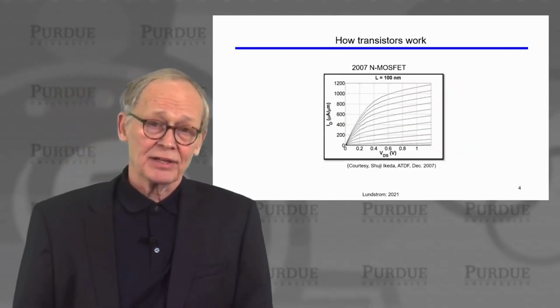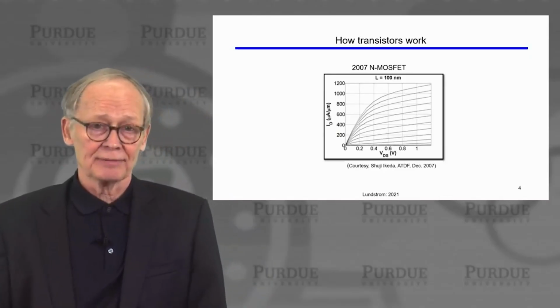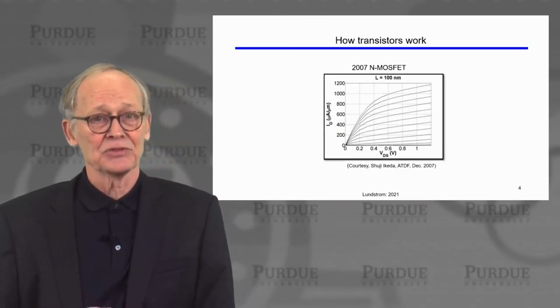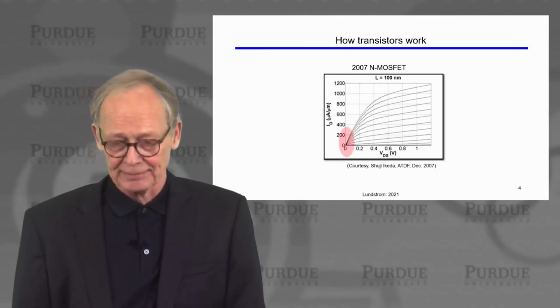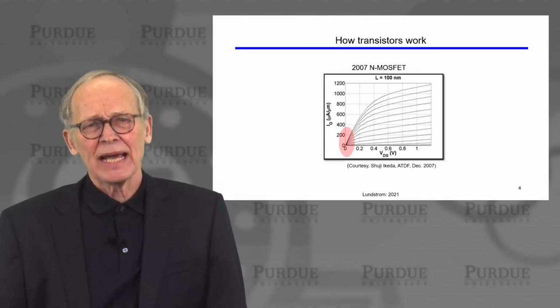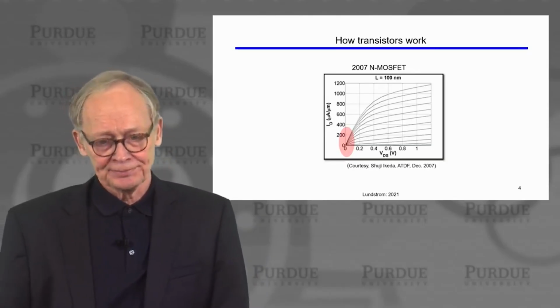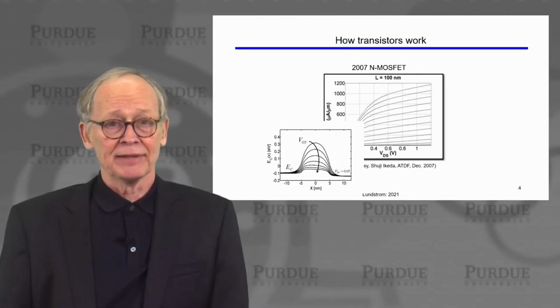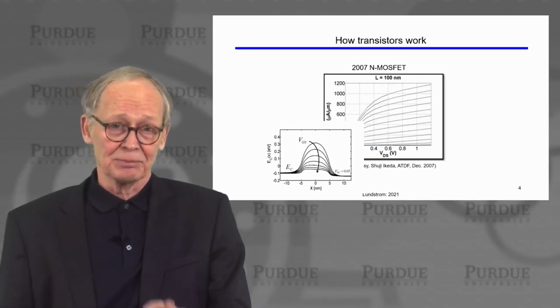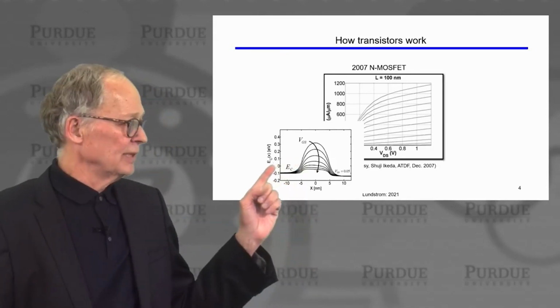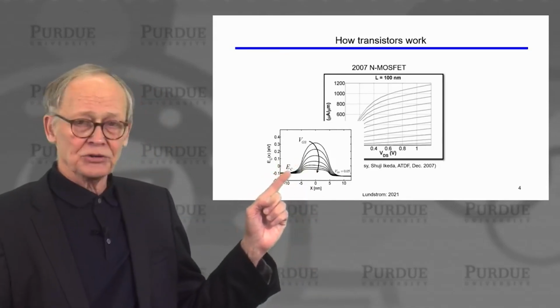Well, these are the IV characteristics of a typical MOSFET. Pretty representative of what we might still see today, although channel lengths are quite a bit shorter today. If we ask, what's going on at low drain-to-source voltages? Well, we can draw energy band diagrams. These are actually computed by a computer simulation. And what we see here is that there's a conduction band in the source.